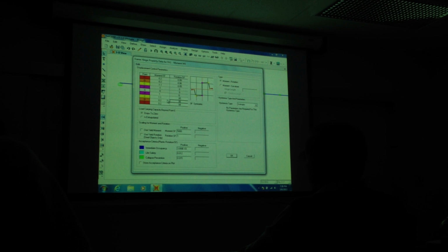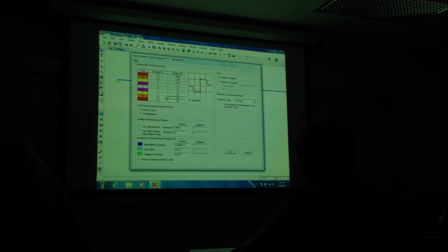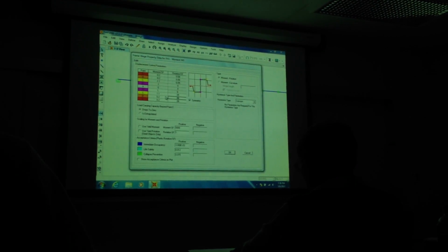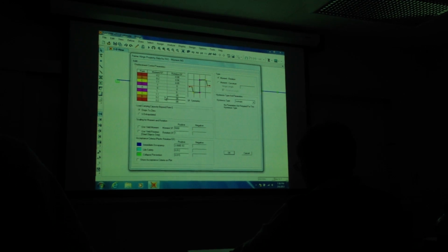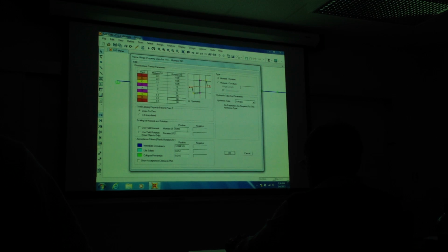That defines the curvature, which is the slope of the strain profile across the section. And when it's linear elastic and when it's nonlinear, the strain profile is assumed to be linear across the section. The stresses are nonlinear, but the strain profile will be linear. So we're good, we say okay.